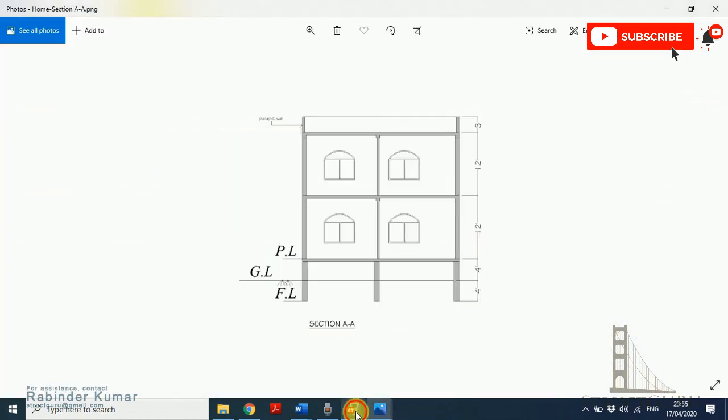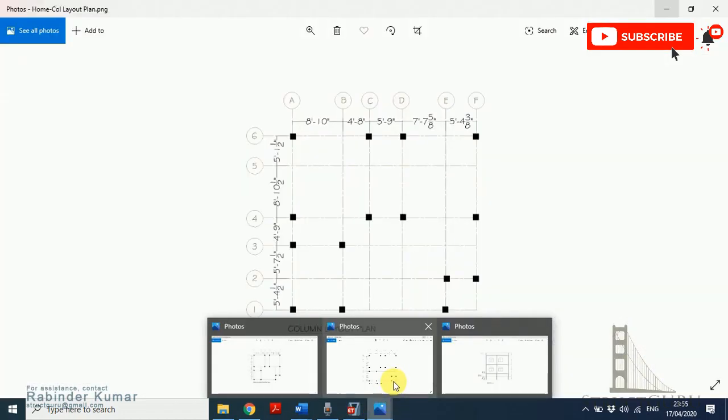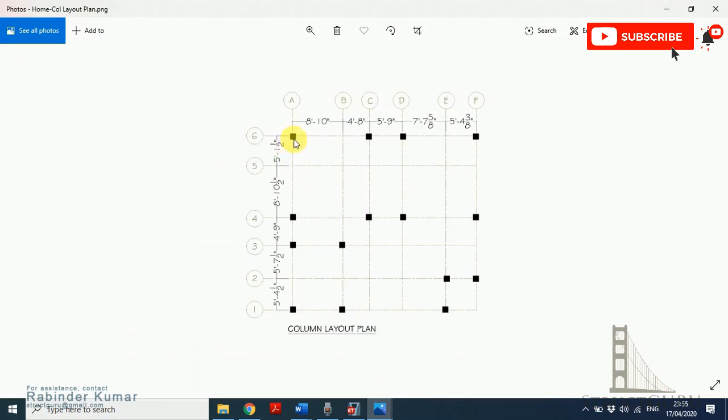Go to your column layout plan and see the location. So along grid A6 there is one column, along grid C6 there is one column, along grid D6 there is another column, along grid F6 there is another column. As you can see, the center line of this beam is not passing through the center line of this column. But for our case, we are considering both lines are passing through the center.